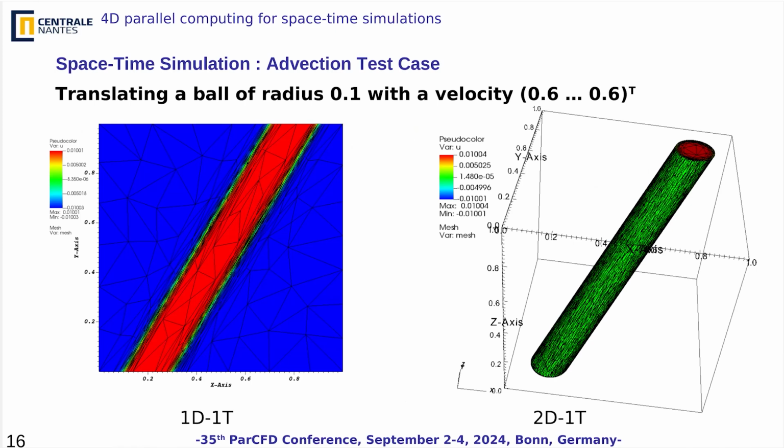The interesting thing here is that you can see that, coupling mesh adaptation, we have some very huge time steps far from the interface, inside the domain also, and close to the interface, we have small time steps. But it's not really a time step, because you can see that the elements are stretched or elongated, not in the time direction or in the space direction, but both in time and space. So doing that, we have a quite optimal mesh.